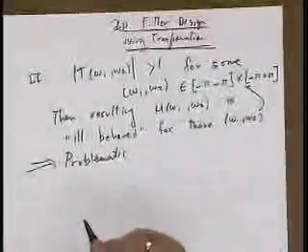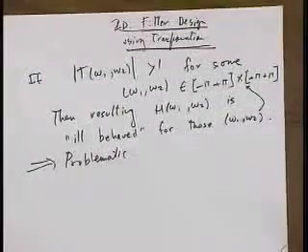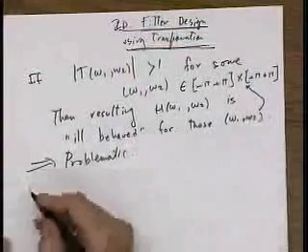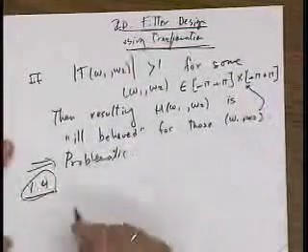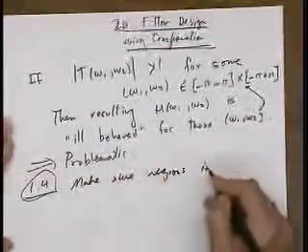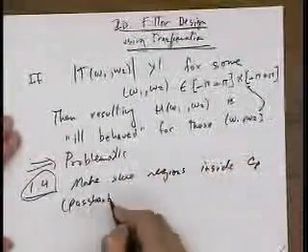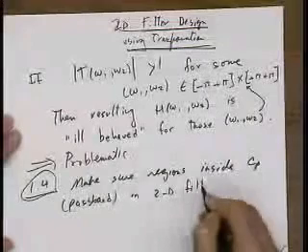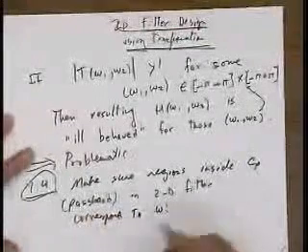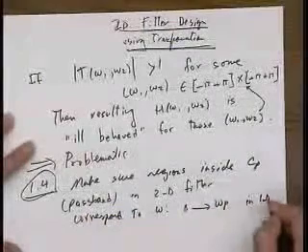So instead, what we want, how do we fix this problem? We go back to step 1.4, and we make sure that the regions inside C sub p, i.e. the passband, in the two-dimensional filter, correspond to omega in the one-dimensional case in between 0 and omega p in the 1D filter.